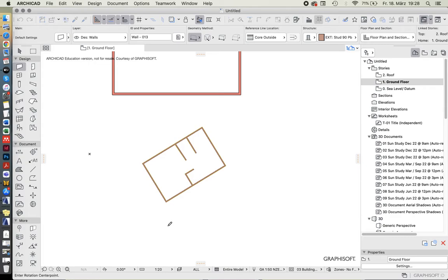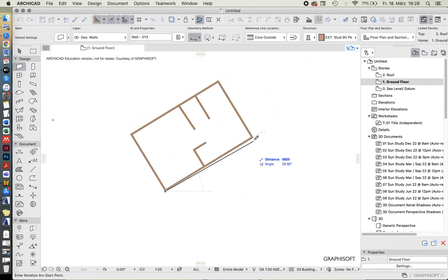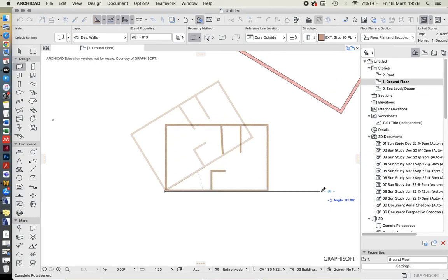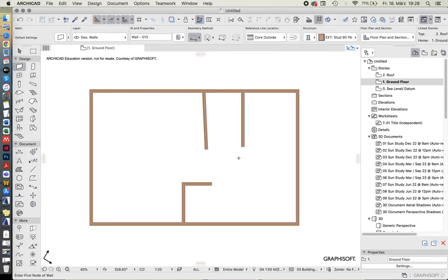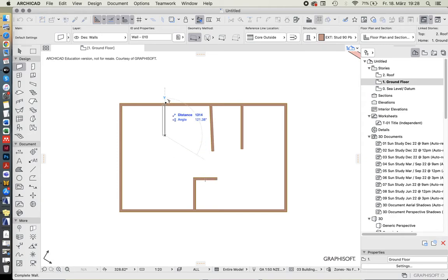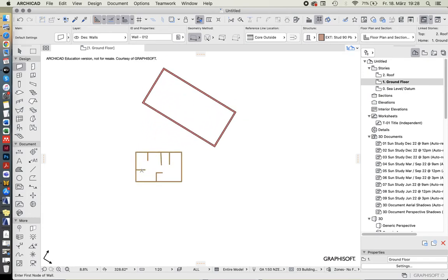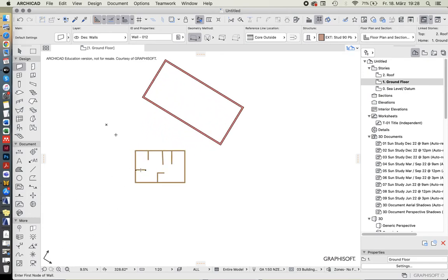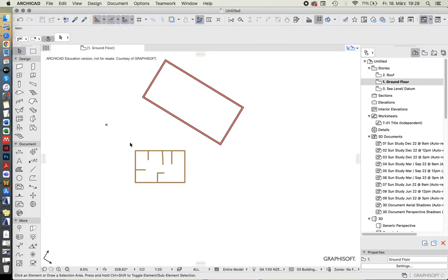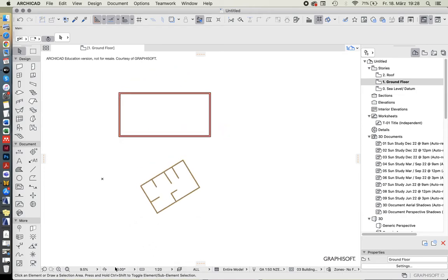That's where it becomes really handy, and you can actually rotate the view as you would want to draw it. So again, having it slightly tilted, now you can draw your walls, and it's much, much easier. So yes, when you set up a project, make sure that you orient it the way that the project will be. Please assume that when your document is set up to 0 degrees, that is north, east, south and west, and then change it at the next step.